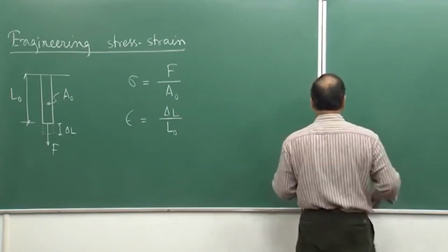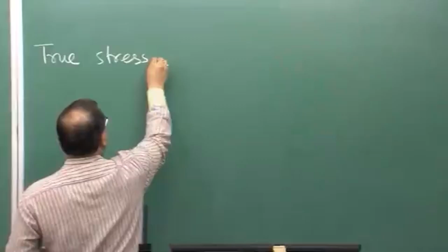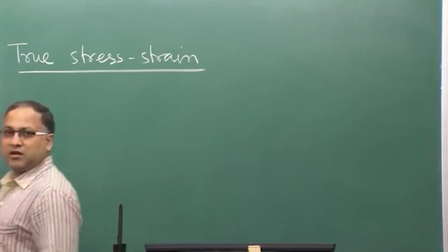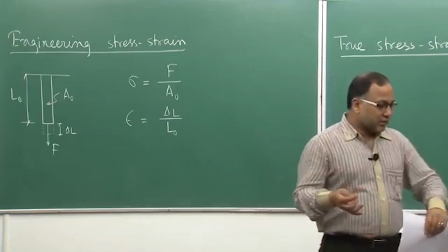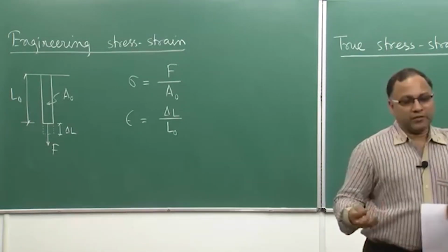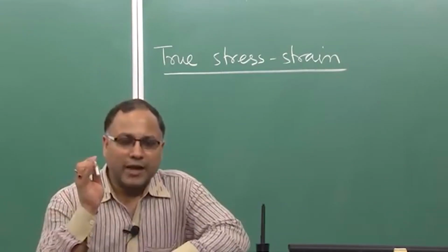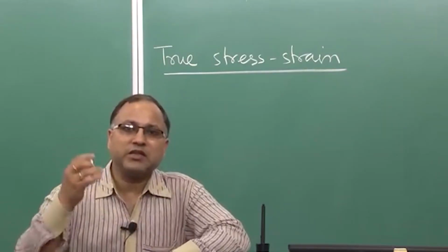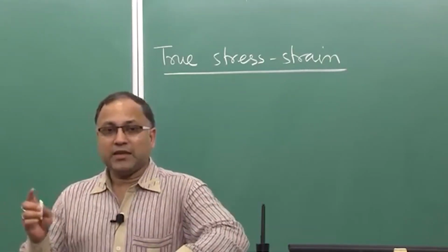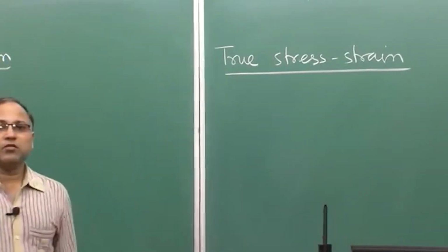So, when we are talking about the true stress strain, why am I saying true? That means the engineering stress strain are not true, they are basically based on the original configuration, right. Frankly speaking, they are not giving you the actual response of what is happening during the process of the test, during the application of load. If you want to capture what is happening at that instant, then you have to talk about true stress strain.